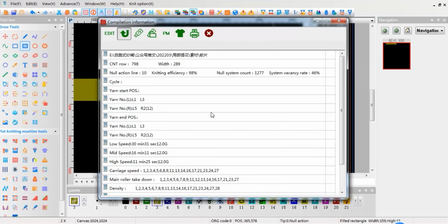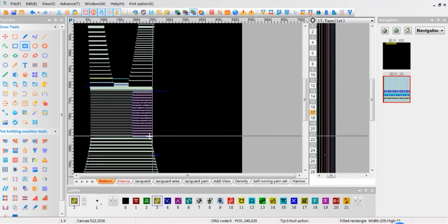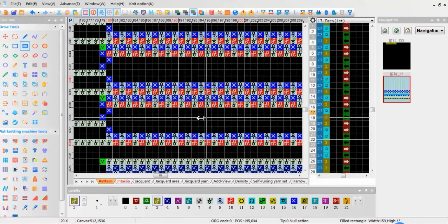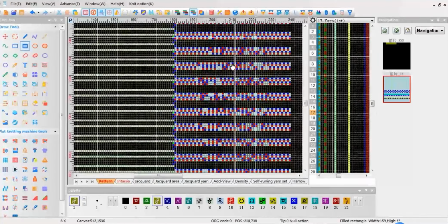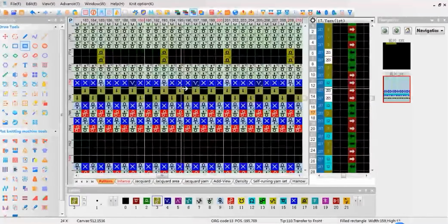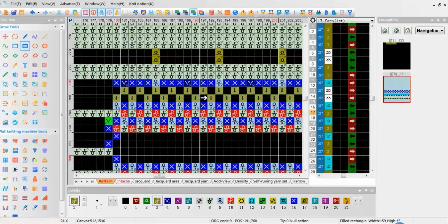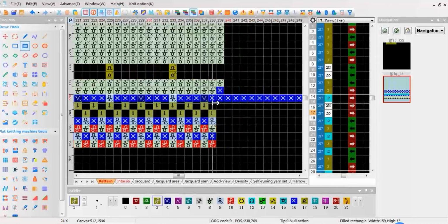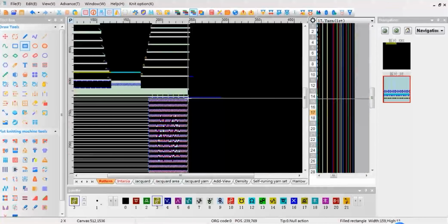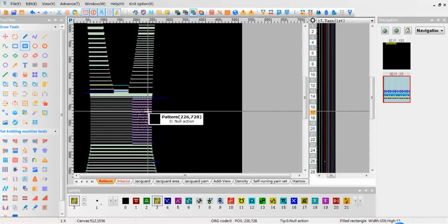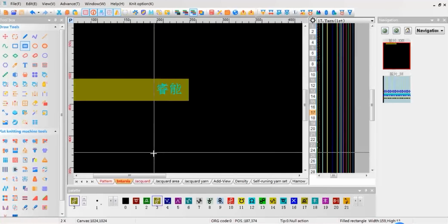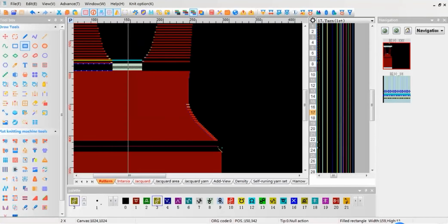View the compiled knitting action file. Singer to JQD. The back knitting form with 1x1A. JQD to Singer with transfer. The number 12 yarn feeder is taken out from the right when finish is all knitting. Knitting with the number 12 yarn feeder on the right, the floating line is relatively short. If knitting with the yarn feeder on the left, the floating line is longer. The above is the 5 steps of drawing ordinary partial jacquard.